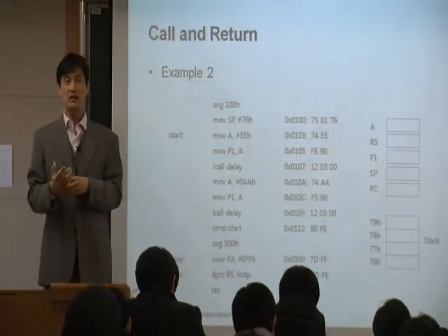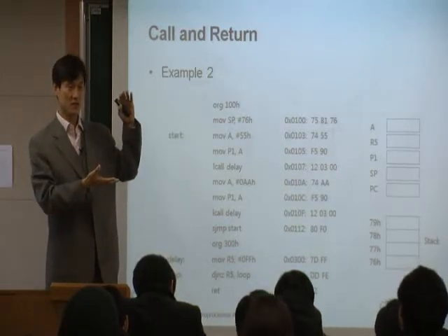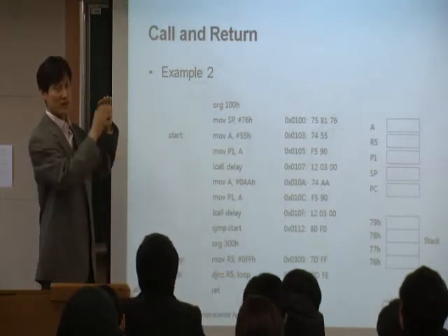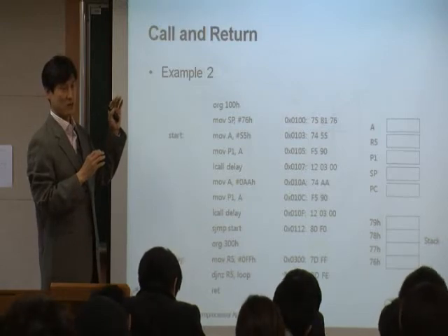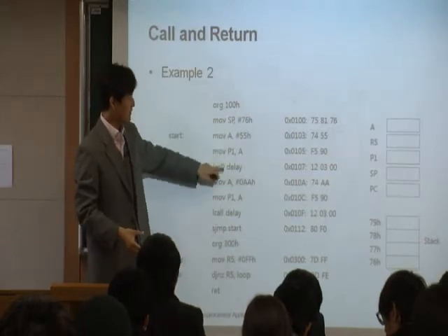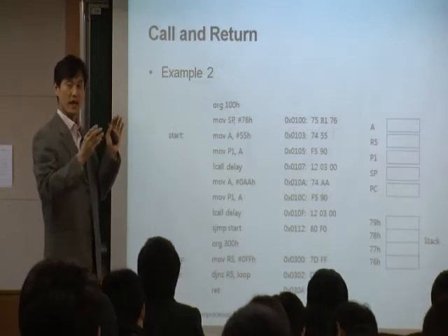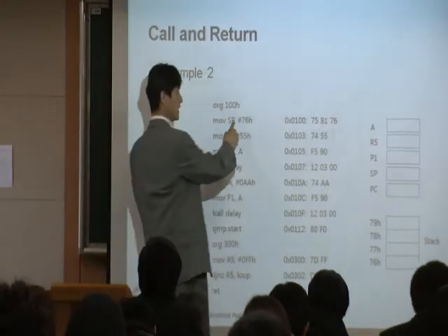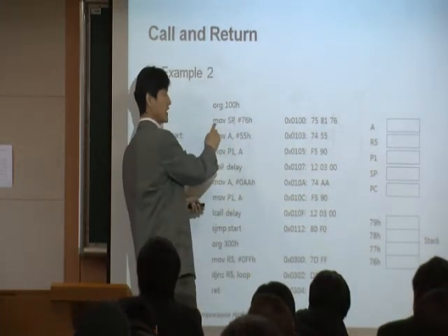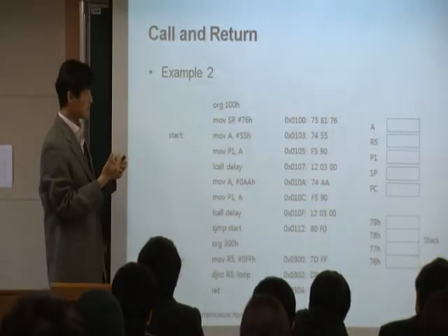You look at the second week of lecture notes. You remember that there is an area called the special function registers. Inside the special function registers, there are some gray areas and some registers defined. When you look at those, all of these registers we use, stack pointer, A, P1, R0, all of those registers have their own address. And stack pointer has the address of 81H. And move in this case is like 75. That's how you map it. That's what the assembler does.